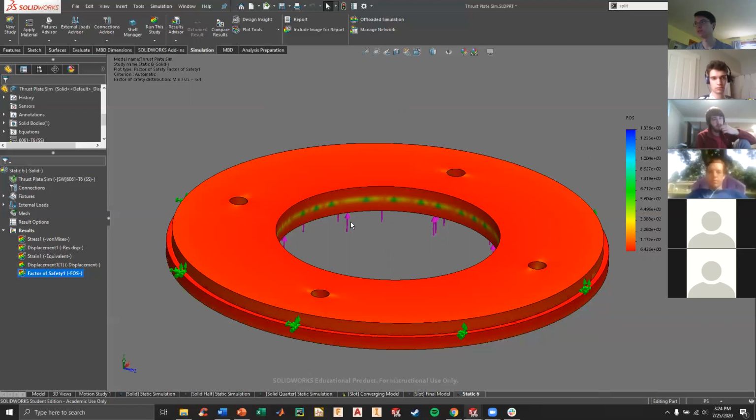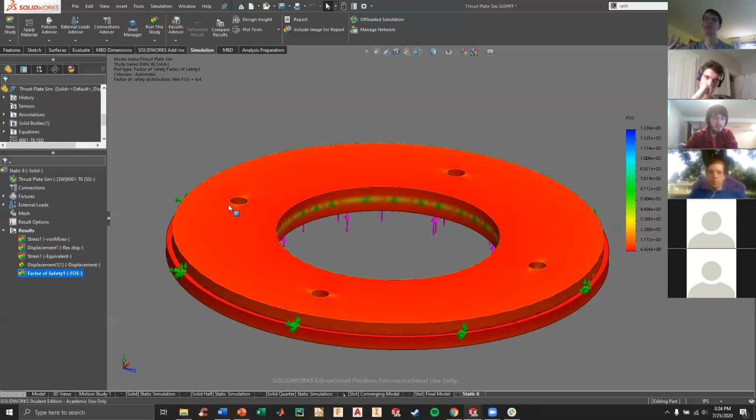Generally, as a general rule, you might use a factor of safety of 3 for most parts. If you're doing aerospace, you can get down to 1.5, maybe 1.25, because you've got to save weight. And for industrial, normal stuff you might find, it will have a much higher factor of safety, 5 or above, just because